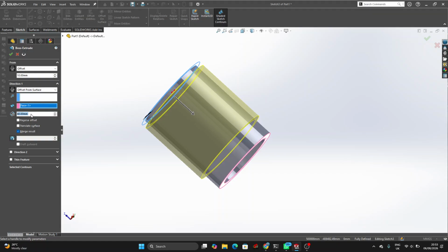I'm usually going to this end face, but I need to offset it from this face by 40 millimeter. If I want to go to this face, I will go upward a little bit. I want to flip it again, to change the direction to reverse it.